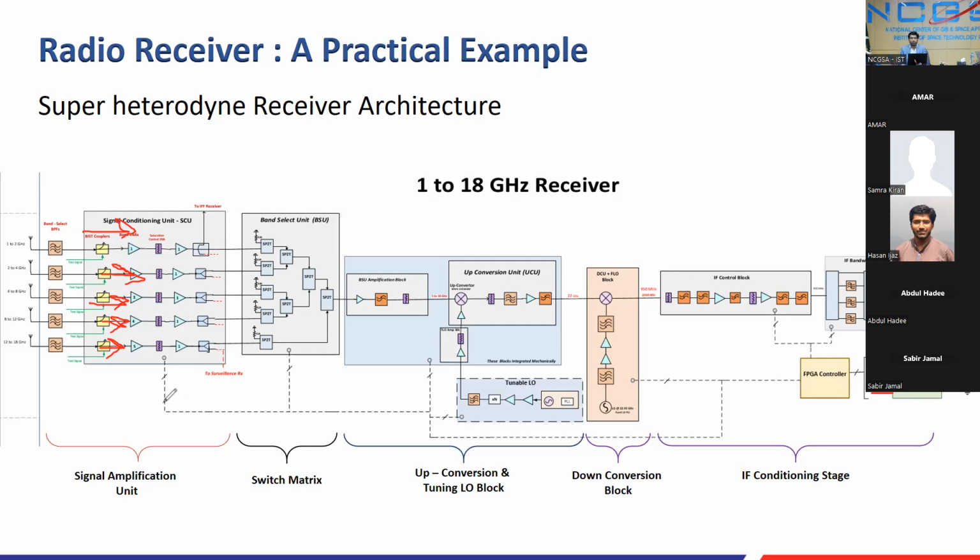For example, in this receiver, you can have a switching circuit at this point, and from one path you inject a test signal, and the other path you may sense the received signal strength. Then according to received signal strength, you can adjust. For example, if in your environment you have a signal of around minus 60 dBm, and your receiver saturation is minus 40, you need to plan accordingly. If the signal power is rising, at this point you can have a decision of receive signal RSSI indication, and your DSP board or FPGA that is controlling every module, it will work.